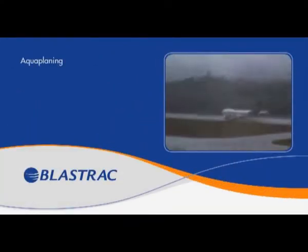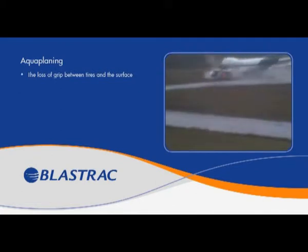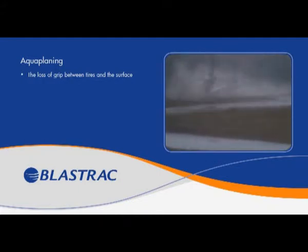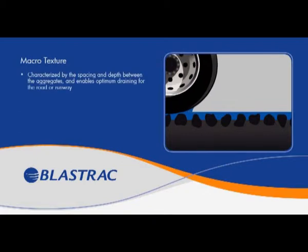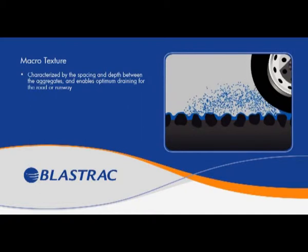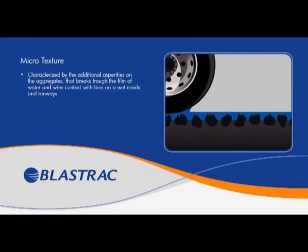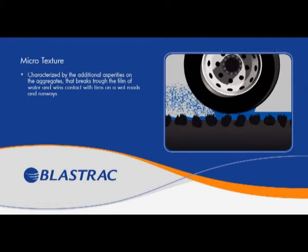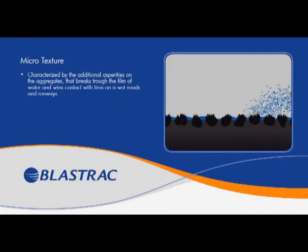The danger on roads and runways during heavy rain is the loss of grip between tires and the surface. When the road or runway is new, it has two characteristics, providing a good grip for tires. Macro texture, which is characterized by the spacing and depth between the aggregates, enables optimum draining for the road or runway. Micro texture, which is characterized by the additional asperities on the aggregates, breaks through the film of water and wins contact with tires on wet roads and runways.